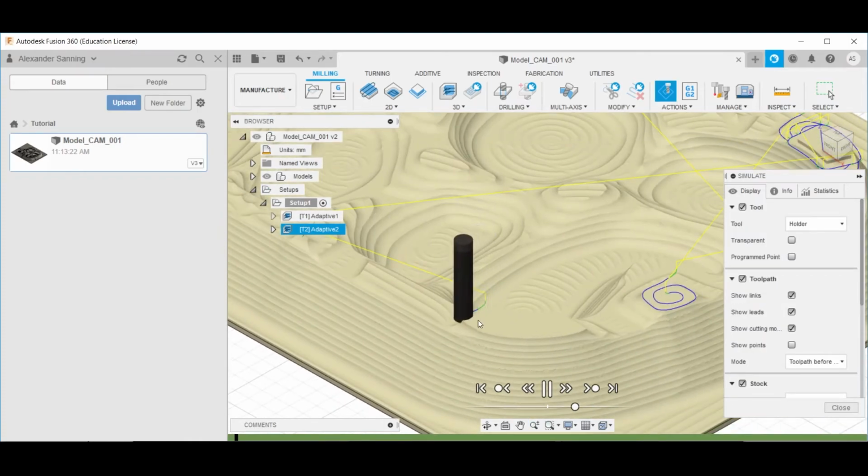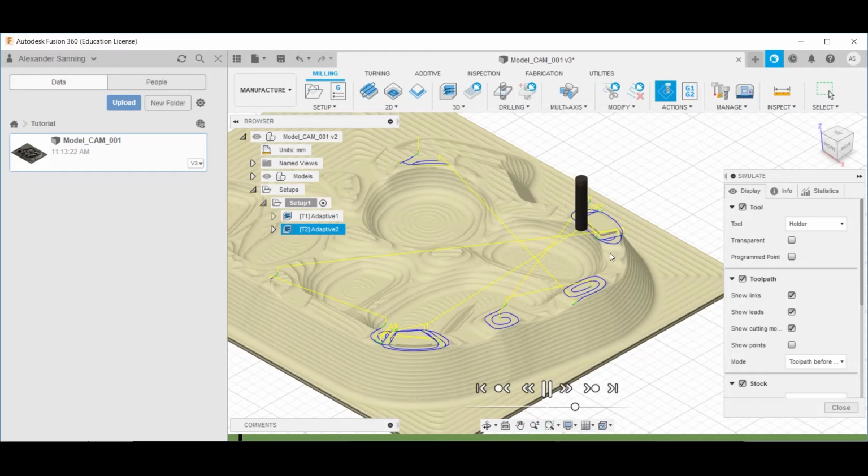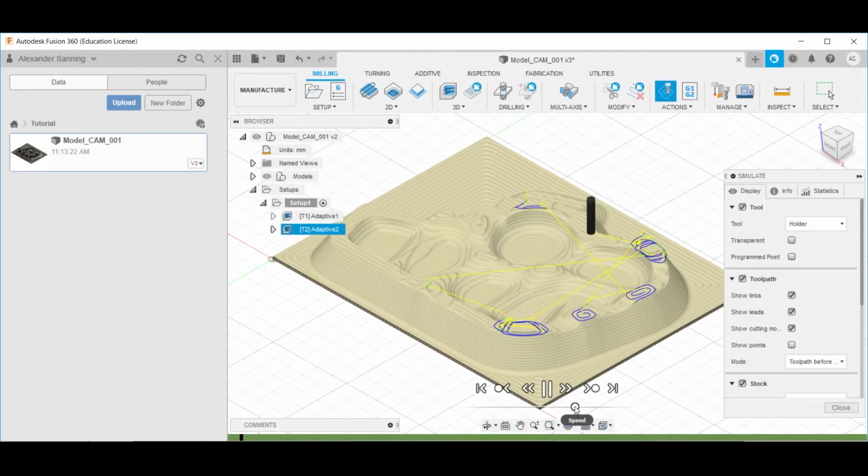And here we see that it first engages in 2 millimeters of the material. And having done so, it goes upwards 1 millimeter and mills away that millimeter as well. So it first engages in 2 millimeters depth of material, and then it defines a final result of 1 millimeter vertical layering or steppings. Very good. Having gotten a grasp of this, we can increase the speed.